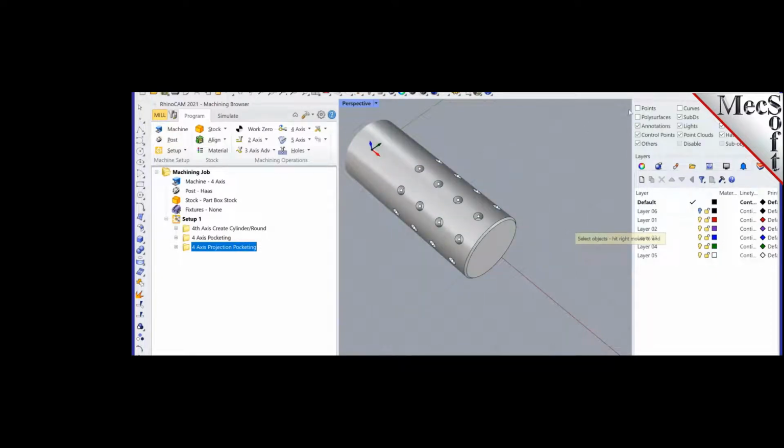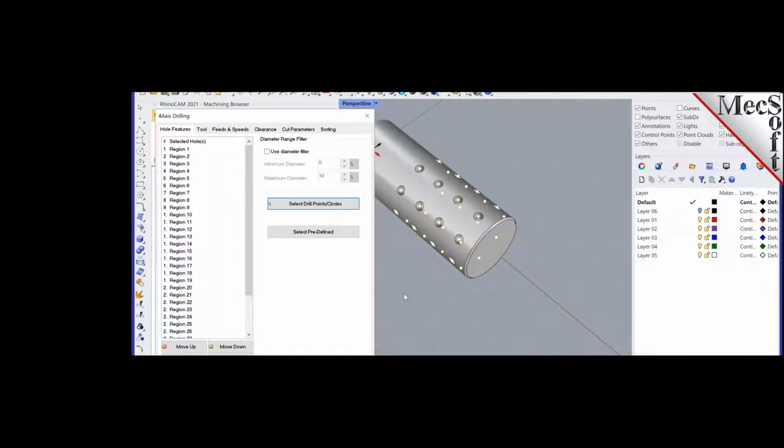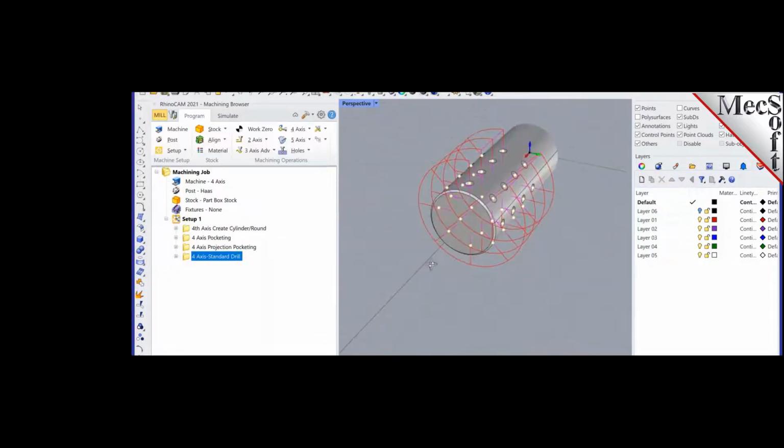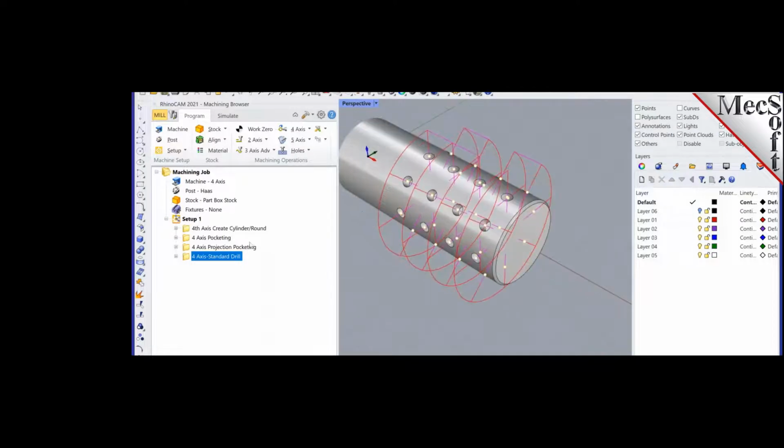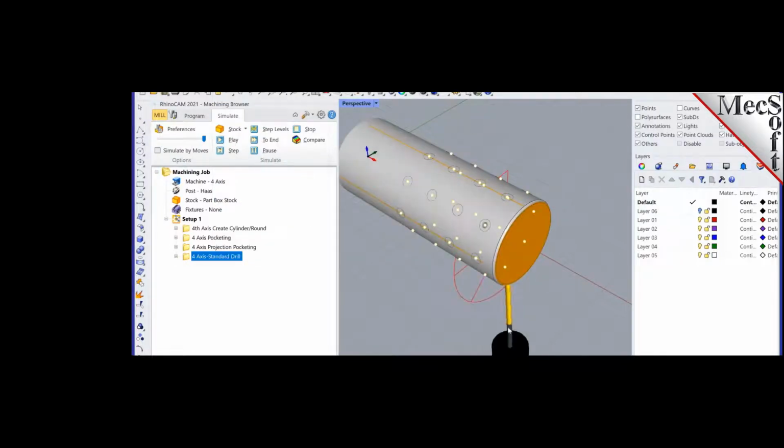I'm assuming your drilling path has pecking and retract above a certain height, etc. Yes, we have all of those. So there's your drill toolpath in 4-axis mode. And we can define cycles, pecking cycles, and also even user-defined cycles. That's not the tool I wanted.